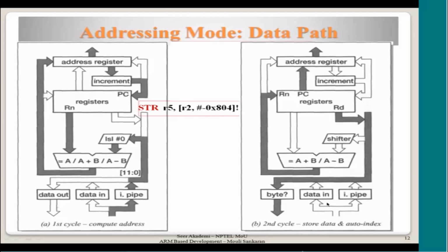That time this data will come through this and there won't be any shift here and it will not take any input. The ALU also will pass this value out and now it will be written into R5. So the memory content coming from memory lands here and then goes through this and finally lands into R5. Till then this instruction is not done until the value from memory goes into R5. So that actually completes the transfer.